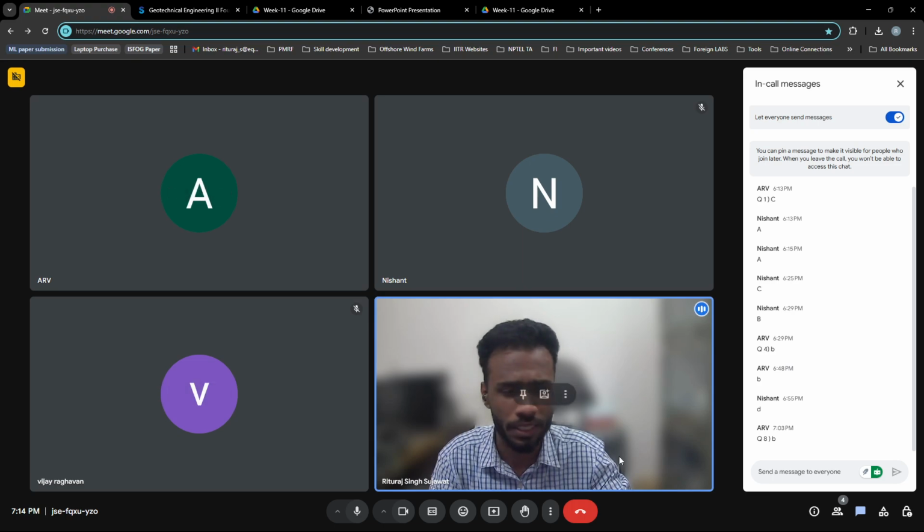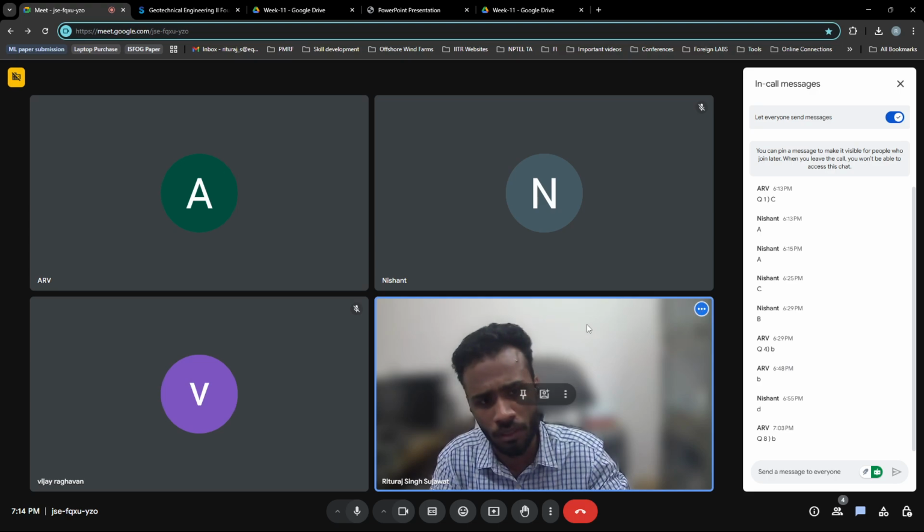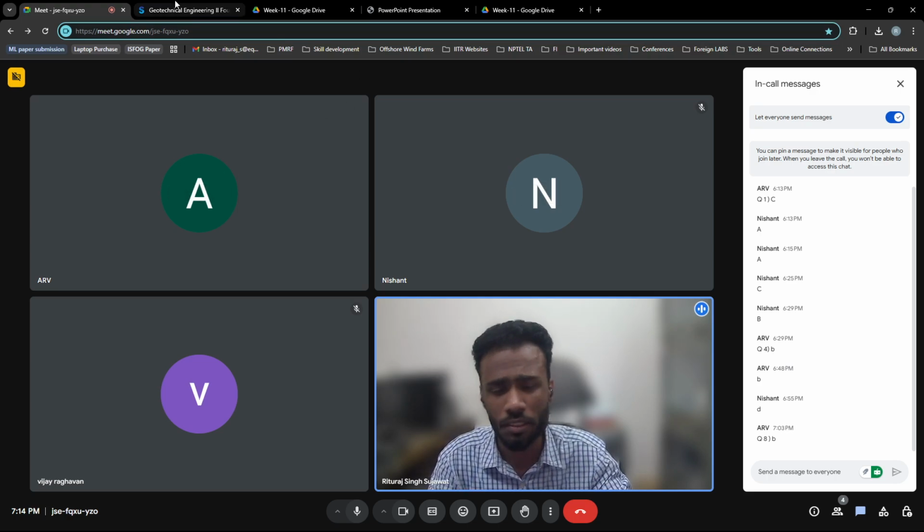So that is how they are designing your sheet pile load. So it's not the entire pressure which is coming. Usually we are having the triangular distribution, but instead they have mentioned the rectangular distribution and they have reduced that distribution by a certain factor by multiplying it with 0.65.